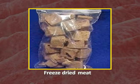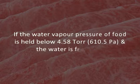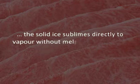In freeze drying, the water content is first converted to ice and then changed into vapor without passing back through the water phase. If the water vapor pressure of food is held below 4.58 torr, that is 610.5 pascals, and the water is frozen, the solid ice sublimes directly to vapor without melting when food is heated.